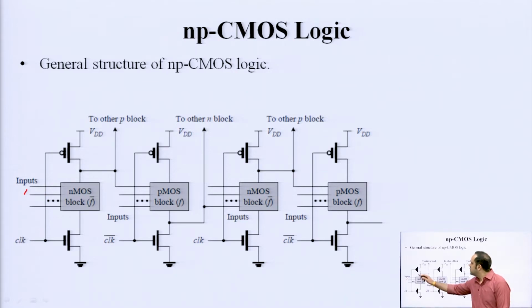In addition, the clock of your pre-charge transistor is connected to the gate of PMOS. The same clock is used for the gate terminal of the evaluation transistor. So, till now it is largely like a dynamic CMOS circuit only. You have a pre-charge transistor, you have an evaluation transistor and you have your logic block consisting only of NMOS transistors, only the pull down network which does the conditional evaluation.